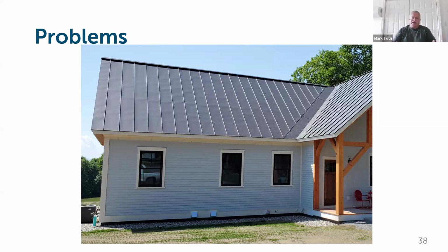So now we have a hole around those two vents, 3 feet wide and 3 feet tall, and it just becomes a cavern for recirculation of air. So this does not work. If it was your own house or my own house, I'd keep it in mind, and I'd have to dig those out every time the roof sheds down, so I keep them free of snow. But either way, they're going to cross contaminate because they're just too close together. So, beautiful house, brand new house, new installation. But once again, this is a place where it doesn't matter how far apart we could get them. There's really no way to get those above grade the way they should be in this application. It's a really tough spot.